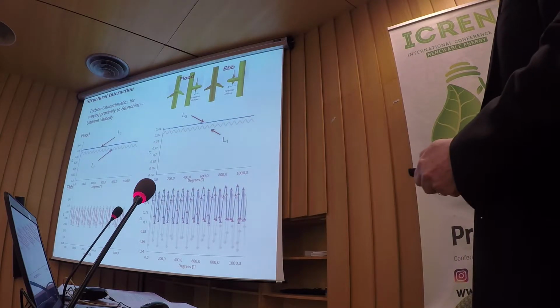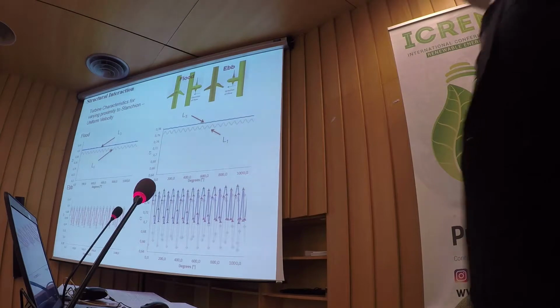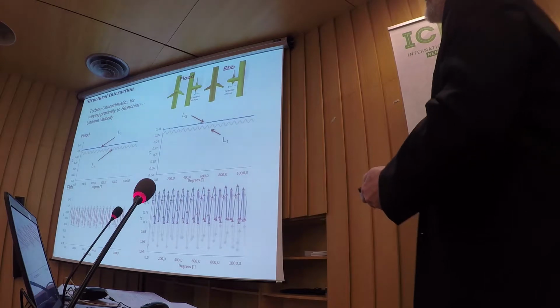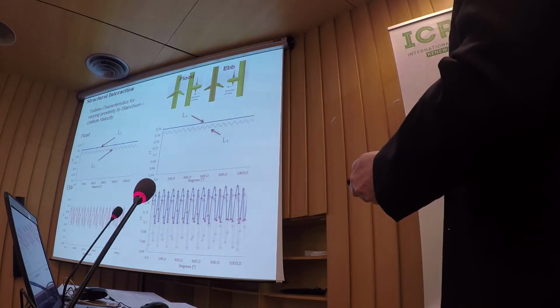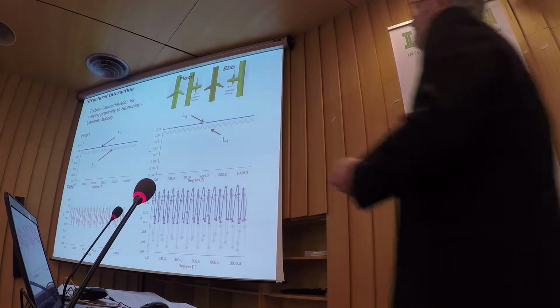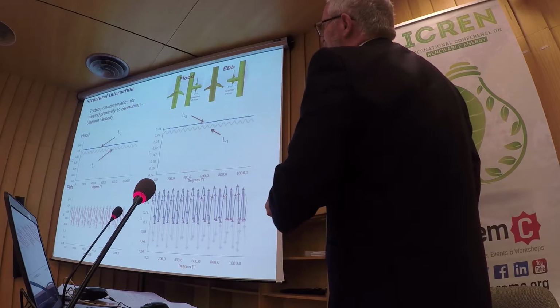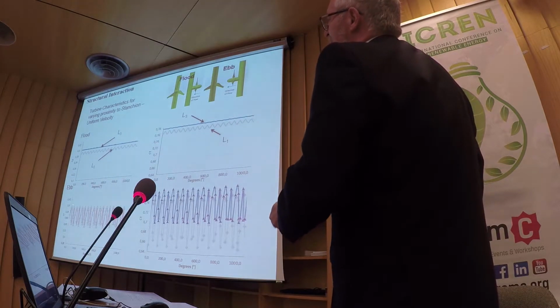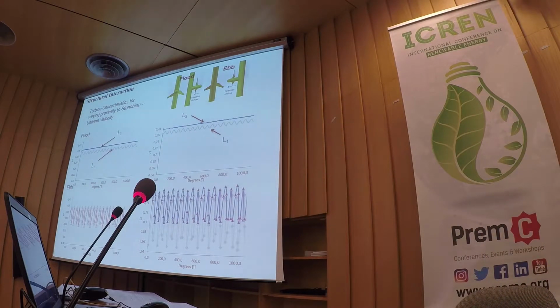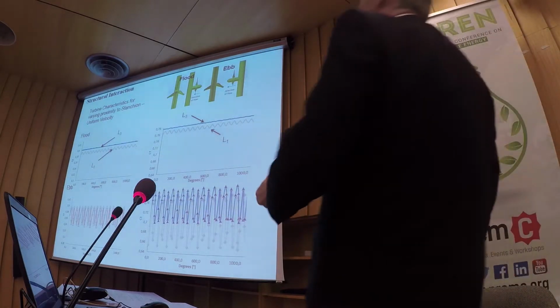At 3 diameters away, it's fairly isolated from the effects of having a stanchion in place. When you get down to 1 diameter, you can see there are some fluctuations when the flow is hitting the turbine first and not the stanchion. If you reverse the flow, that power you can see is far more oscillatory. So automatically the power is going to have to be cleaned up. The power companies do not like having fluctuating power.